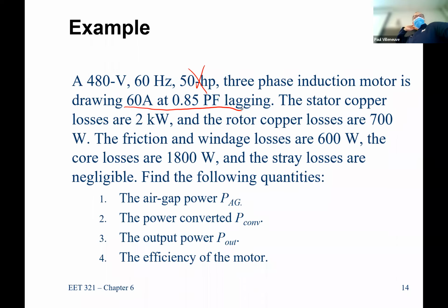It has nothing to do with the load. You might have a little bit of a change if you're not running at full output, but the nameplate rating of that motor is, if you're delivering full output, it's going to need 0.85 lagging power factor operation. So yes, that is all determined by the motor. And that's because look at those big inductors. Go back to our transformer equivalent circuit. We've got a lot of inductors. So we're stuck with it. Okay.